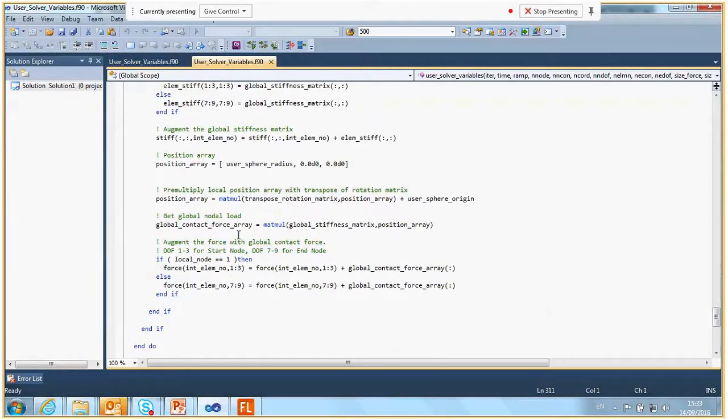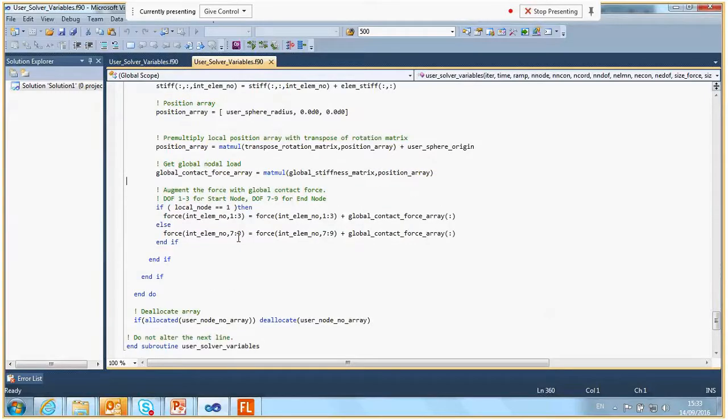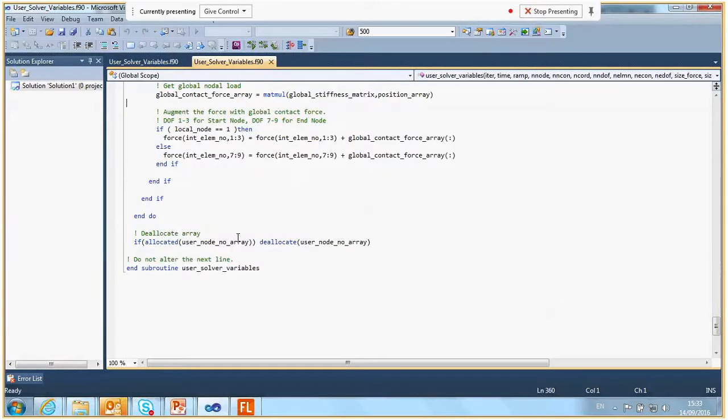And then right at the end, it adds on a right-hand side term as well, just to compensate for the fact that the stiffness term doesn't kick in until contact is made, because Flexcom solves for position in space as opposed to displacement from initial position. So when you add on a new stiffness term to model contact, you actually have to add on a restoring force term as well, just to cancel out the force being applied before contact is made. We don't need to get into too much detail there. That's very in depth and maybe beyond the scope of this introductory presentation.